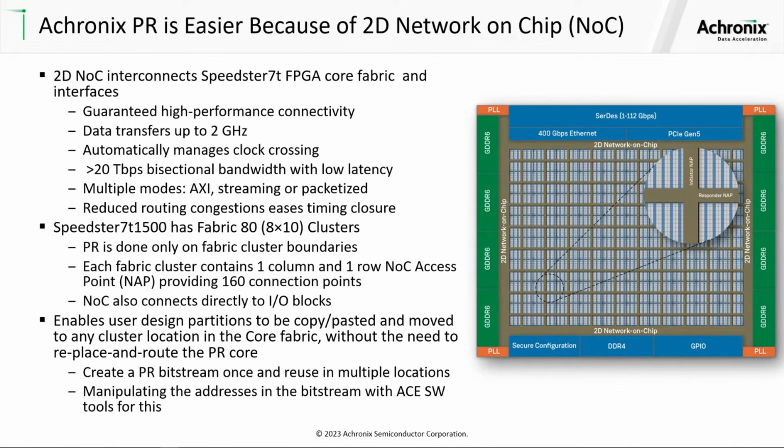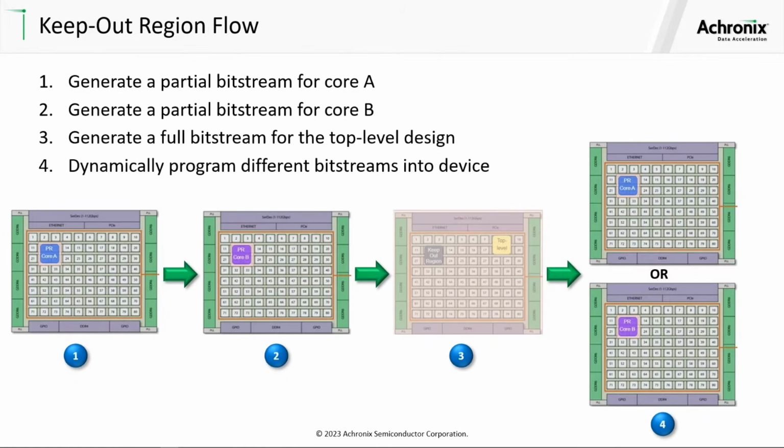But also, the way that this works is because it's connected to that 2D NOC, you're really just manipulating the address at which that IP lives. And we give you software within our ACE development environment, a software tool, to actually do that without needing to customize and recompile every time. So, huge advantage. If you need to learn more about the 2D NOC, we have an introduction training to the 2D NOC as well.